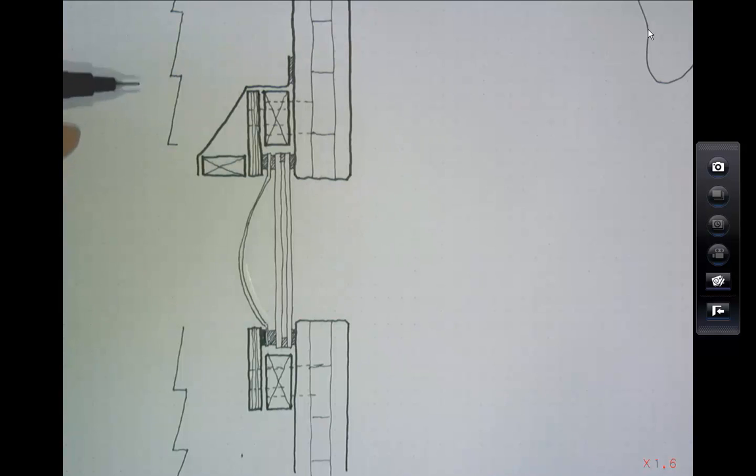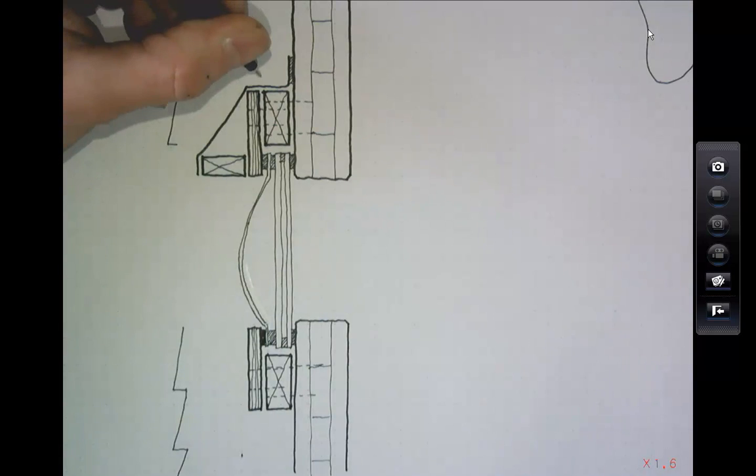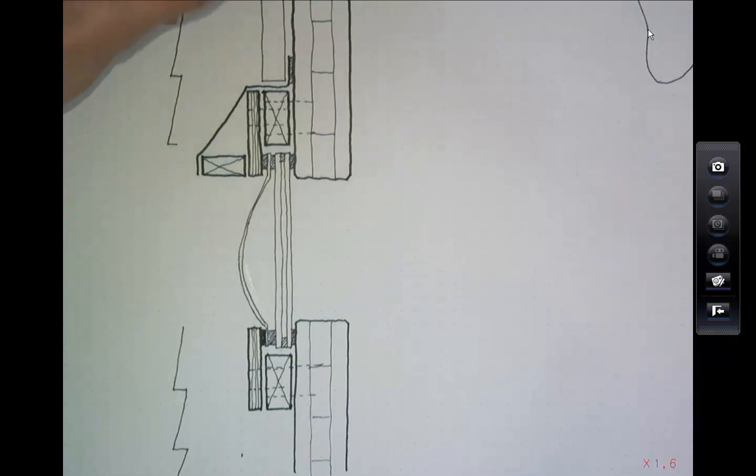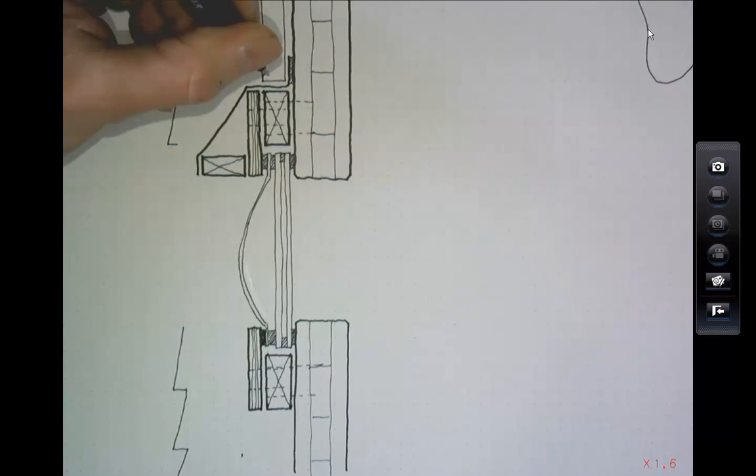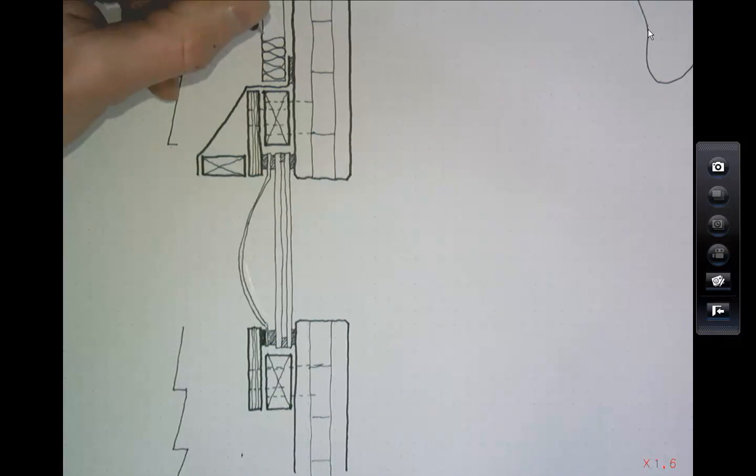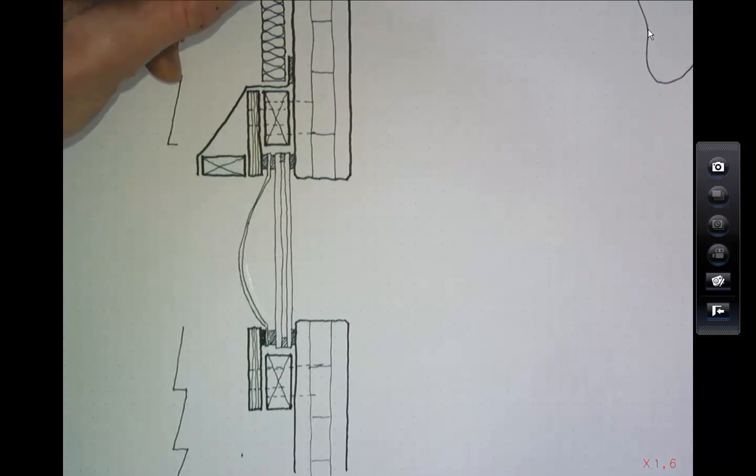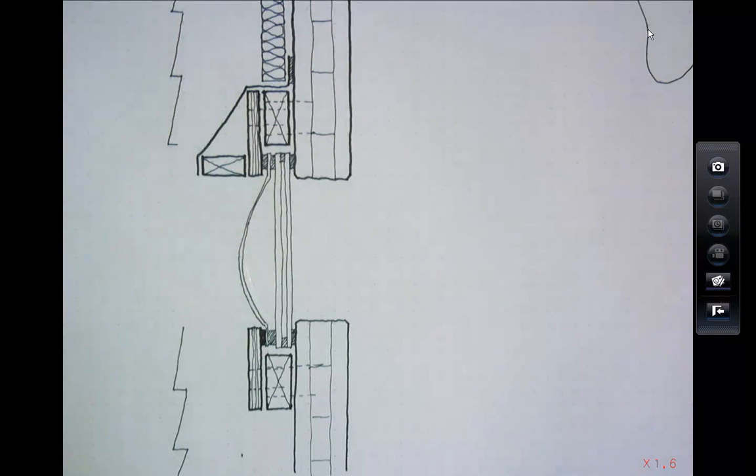Then they've got a really pathetic amount of insulation. Looks really thin, but anyway, I'll draw what they've got. They are showing, I suspect, a 50mm closed cell foil-faced insulation in here. I mean, 50mm will be adequate, but you'd normally try and get a bit more than that in, to be honest.